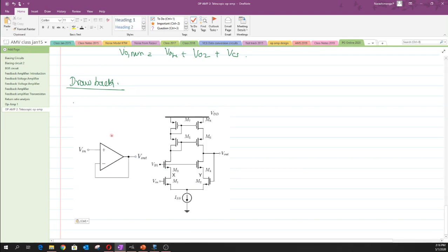Okay. So here is the case as we had discussed in stream number 2 of op-amp, where we had a unity gain feedback amplifier, but this op-amp was being realized by making use of a simple configuration, and we found that the output swing, or basically the input common mode range, is the same as we had for an open loop configuration of a differential pair, which is a simple structure.